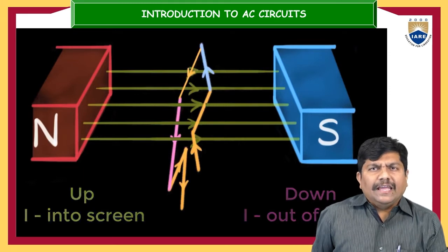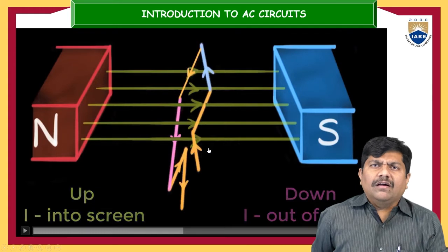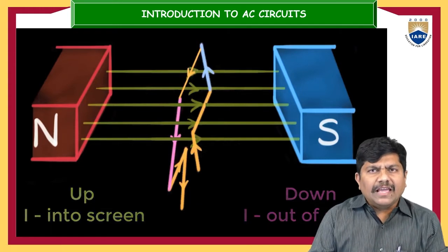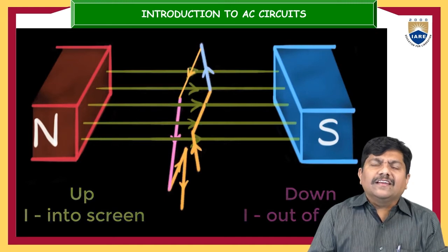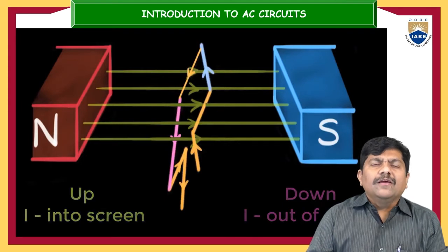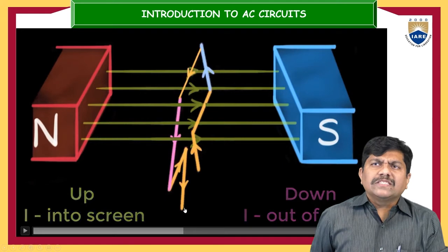So it means any conducting system, any armature conductor or any conductor, if it is revolved in the magnetic field, the same conductor will allow the current in both directions. For a certain period it is positive, and for the remaining period it is negative. So it happens alternately. Because of this, the output across these two terminals, the voltage, is like the current, alternating in nature.